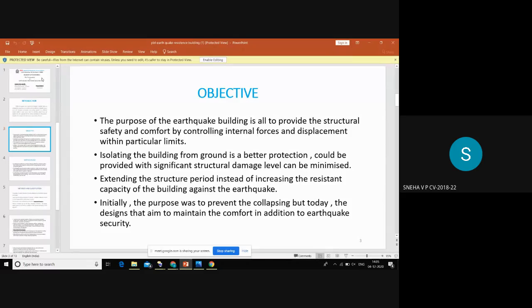Here we have the seismic isolators, which are seen to be an effective solution within this context. They are placed in the building appropriately to damp the seismic energy, placed between the foundation and the vertical structural systems, damping the seismic energy under the ground of the building. By this, we can decrease the effect of lateral loads which come on the top floors. Over to Srishti.